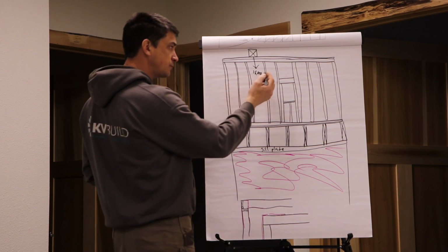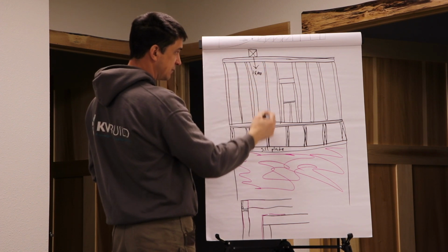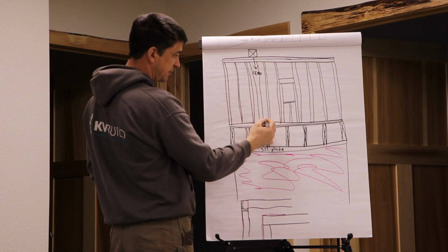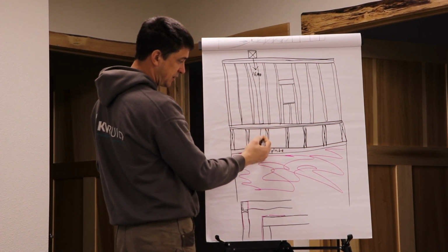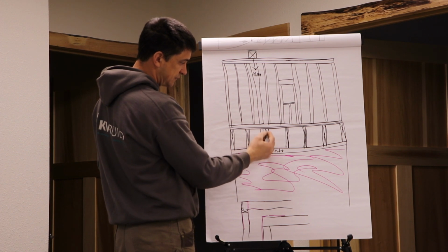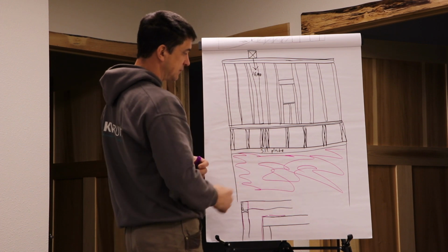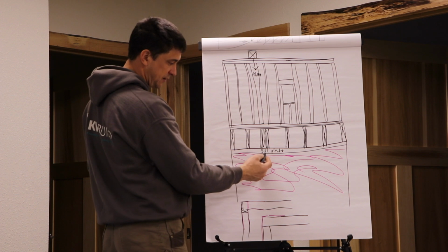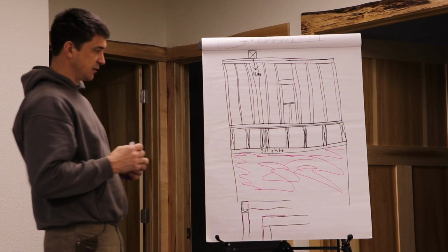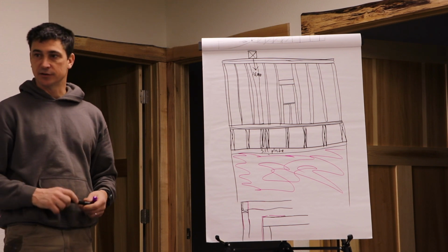We can look up in the code, but we would have some type of framing underneath that beam that runs down to our sill plate. Then we would come down in this space and put some blocking in here of some sort to fill up the space underneath that beam to transfer that load to our sill plate, and the sill plate is sitting on our concrete, so then we've effectively transferred that load all the way to the foundation.